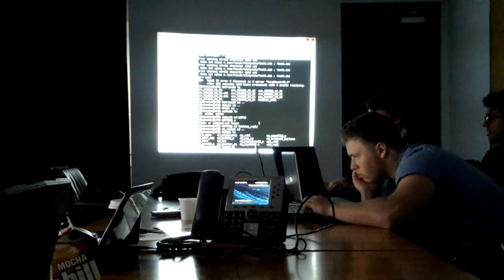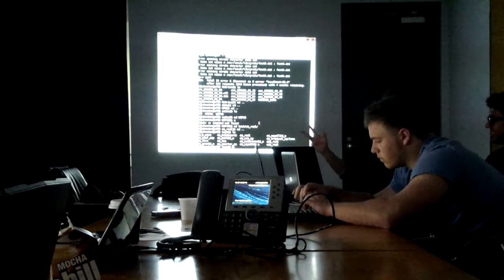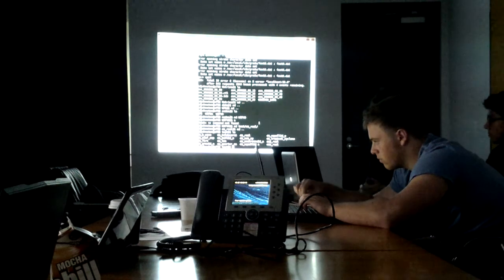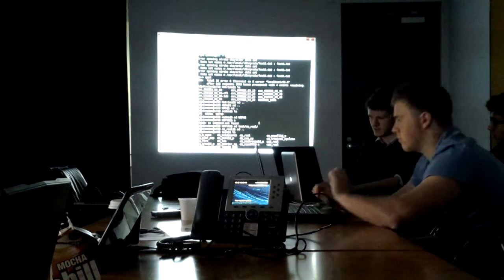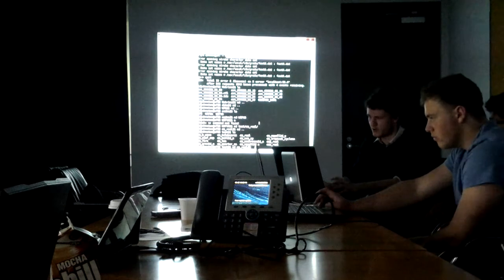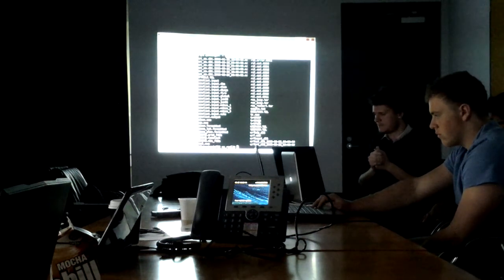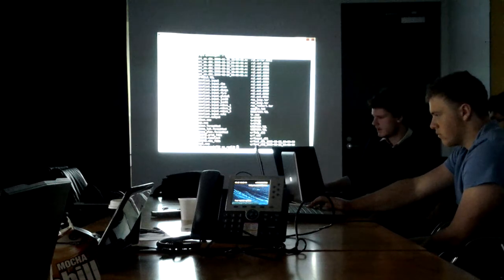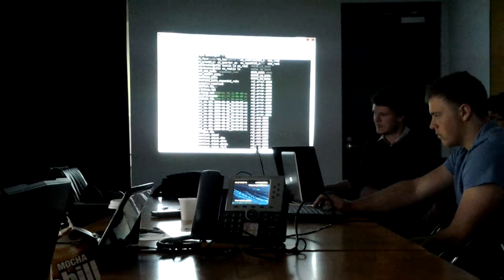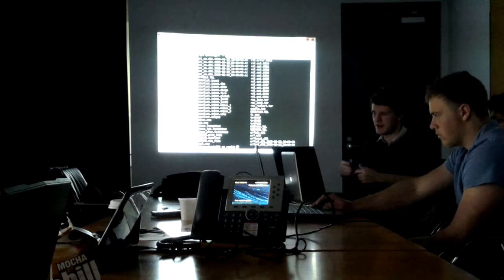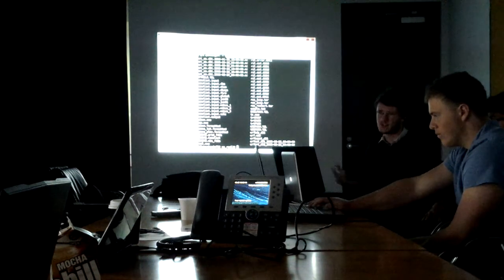As you can see, these are all the idealized cases I was talking about before, a sort of trivial simulation of ideal systems. So they're all the different simulations that come prepackaged, where you can program your own. Otherwise, there is the real directory, which is where you simulate your real case. So these are symbolic links to your pre-processed data. Then you run WRF, and it sort of churns around for a little while. It takes a while, so I won't run it.